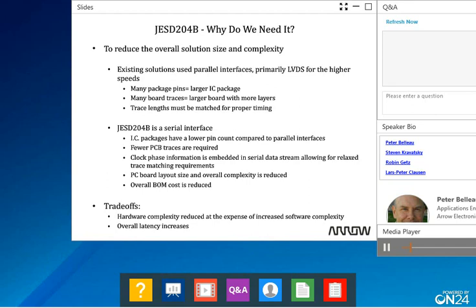For an 8-channel 16-bit DAC, this would require over 100 pins just for the samples. More package pins also meant more PC board traces, resulting in a multi-layer board. On top of that, the board traces had to be matched in length for equal propagation delays, so the data will all arrive at the same time. This increases the board size even further.